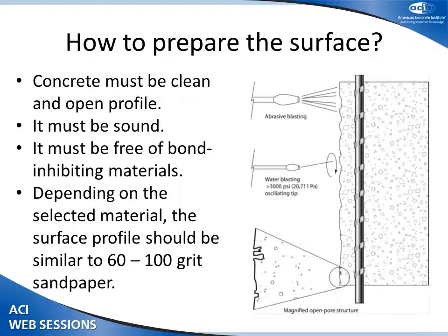So how do we prep that surface? Looking at the slide on your right-hand side, take a look at the bottom of the illustration there. The surface is imperfect. The greatest fallacy out there is that concrete is indestructible and maintenance-free. When we deal with concrete, how was it placed? How was it consolidated? What type of forms did we use? What type of liners were in the forms? What type of release was on the forms? All questions that need to be considered. But what we're dealing with now is the aftermath.